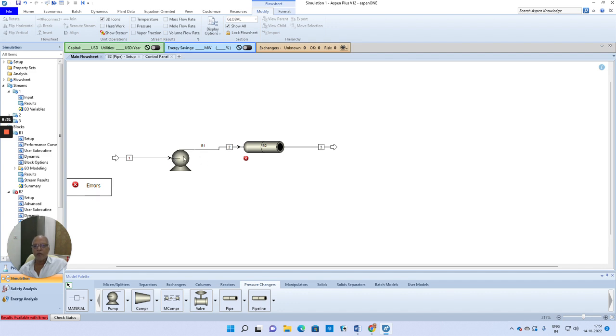So that means we need to increase the pressure to which this liquid must be compressed in order to handle this pressure drop so that flow will happen across the entire pipe and you should be in a position to deliver. Ideally, unless the pressure coming out of this pipeline is slightly more than the atmospheric pressure, there may not be any flow happening. So it should be able to handle the entire pressure drop in the entire pipeline, and the exit pressure must be slightly above atmosphere.